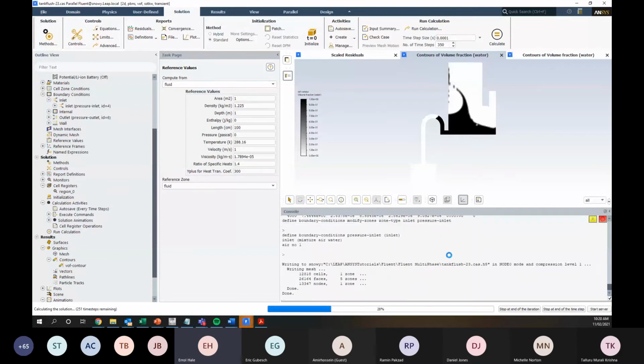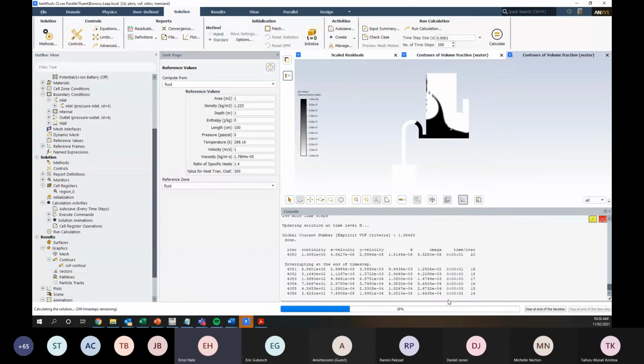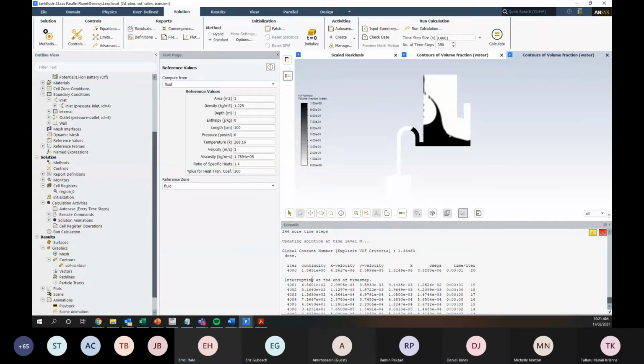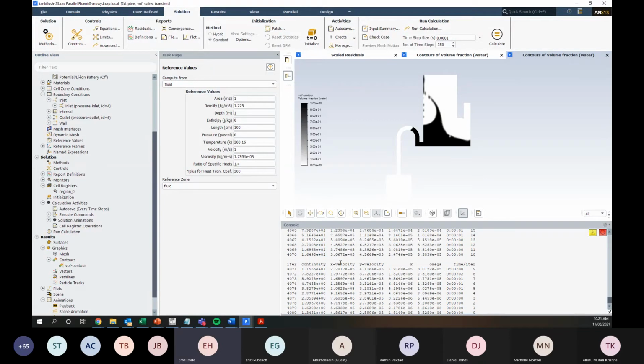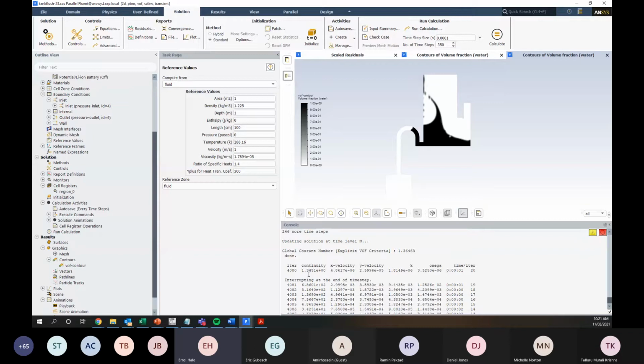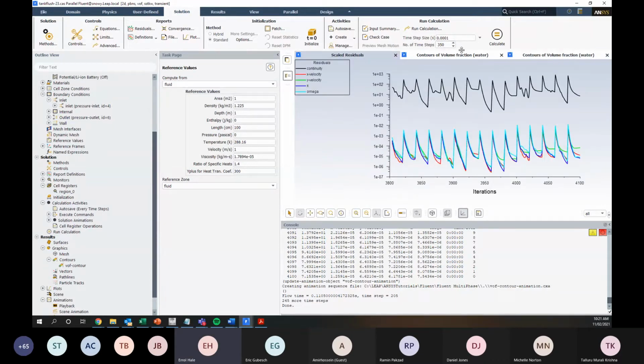But you can see also another way we would know that there's a problem with convergence is it's going through all 20 iterations per time step. So if I was to stop at the end of the time step, you can see that each time step, so 246 more time steps to go, is going from 20 iterations down to 0, and then into the next time step, 20 down to 0, into the next time step. Yeah, so there's definitely some work that needs to be done to improve the convergence behavior of that model.